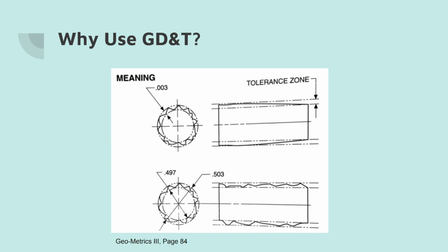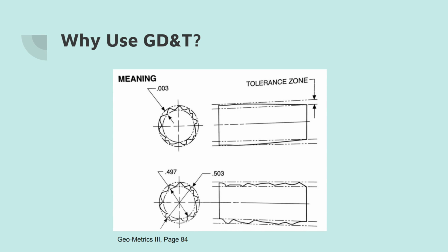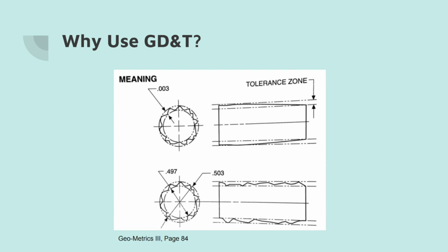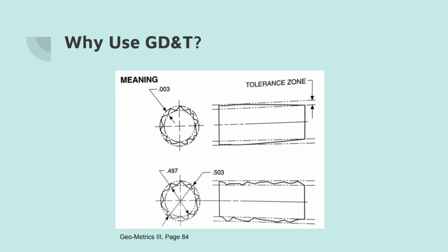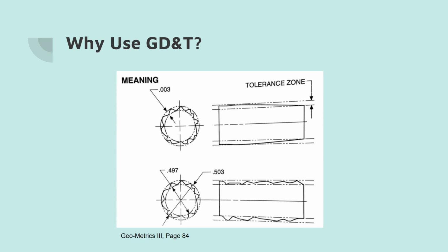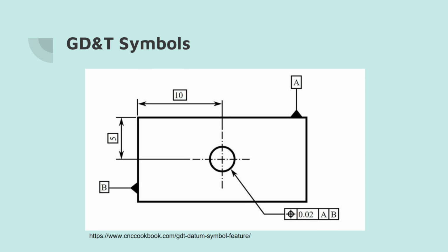If the cylindricity tolerance zone is larger, the company will be able to be more lenient during the manufacturing process, as the surface finish will not need to be as smooth. For example, in figure 3 above, all points on the surface lie within the tolerance zone, although neither looks particularly smooth, so these parts are acceptable. However, if the tolerance zone was made smaller, the company would need to spend more money to make the surface more precise. Many of the different types of tolerances use a datum as a reference.